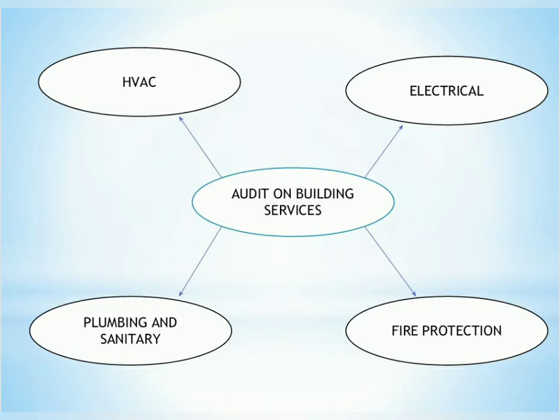As a periodic system, failure is expected in an HVAC system. The restoration of the system to its normal operable state in a given timetable is important. Neglecting preventative maintenance for components which require energy sources will reduce the HVAC service life, resulting in untimely HVAC component replacement and a spike in operational cost. The maintainability of the HVAC system should be considered during the design stage to ensure adequate access for inspection, maintenance and repair of all the components.